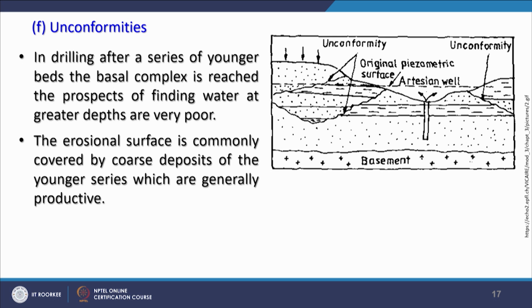So, a myth exists among common people that if you do more drilling you may get water at greater depth. It is not true. It all depends on geologic conditions. So, depth is not as important as understanding the geologic conditions of that local area. Even if a well is rightly sited, if that choice is there, then water for all the time may be available even at a shallow depth rather than going for deep wells.